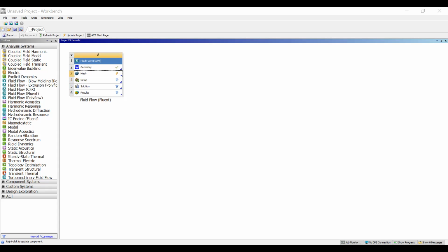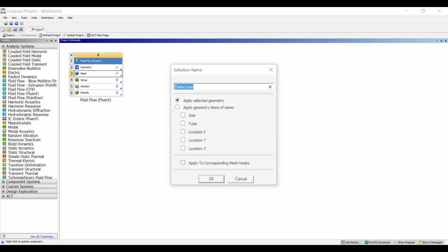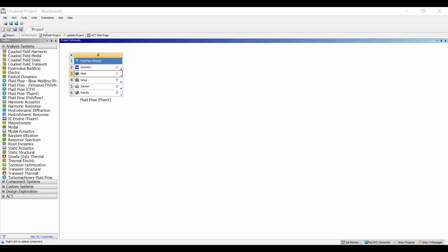Our right edge, we're going to write as our pressure outlet. Perfect. And then we'll click on both our top surface, and then I'm just holding control to hit the bottom surface as well, so that we name both of those. We're just going to call those symmetry. And then our last one, I'll zoom in as we click on this inner edge selection, and that will be our center wall.